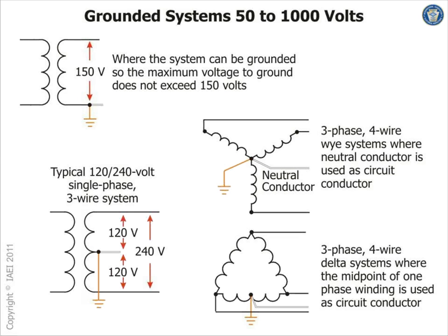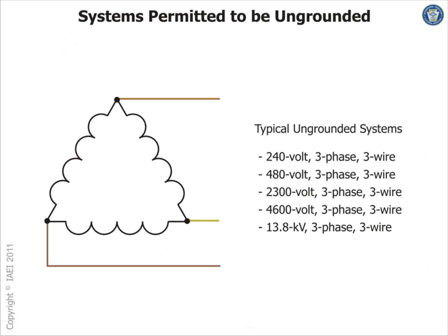Concept number 2, stabilize the voltage to the ground and get rid of all transient voltages that the system might encounter. So if you have a grounded system, your chances of suppressing the transient voltages are much higher than if your system is ungrounded. So that's what I want to start. You're looking at an ungrounded system.